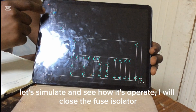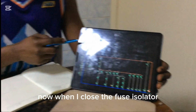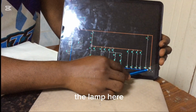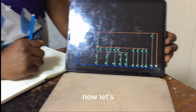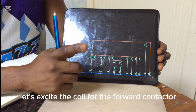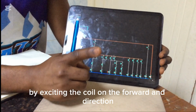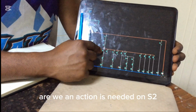I will close the fuse isolator. Now when I close the fuse isolator, you will see that the lamp indicating the presence of supply is already on. Now let's excite the coil for the forward contactor and see how the circuit will behave. By exciting the coil in the forward direction, an action is needed on S2.